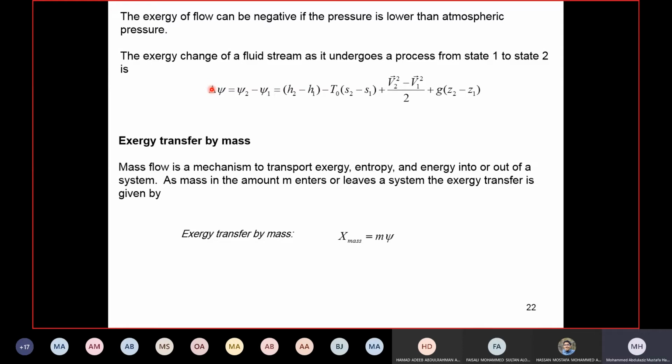So this is the reversible work, so now we can calculate the exergy at another state, and we can calculate the reversible work. Also, this reversible work will be equal to what? It will be equal to W actual plus irreversibility. So reversible work we can calculate from thermodynamics 2 here, or as previously we calculated from thermodynamics 1.